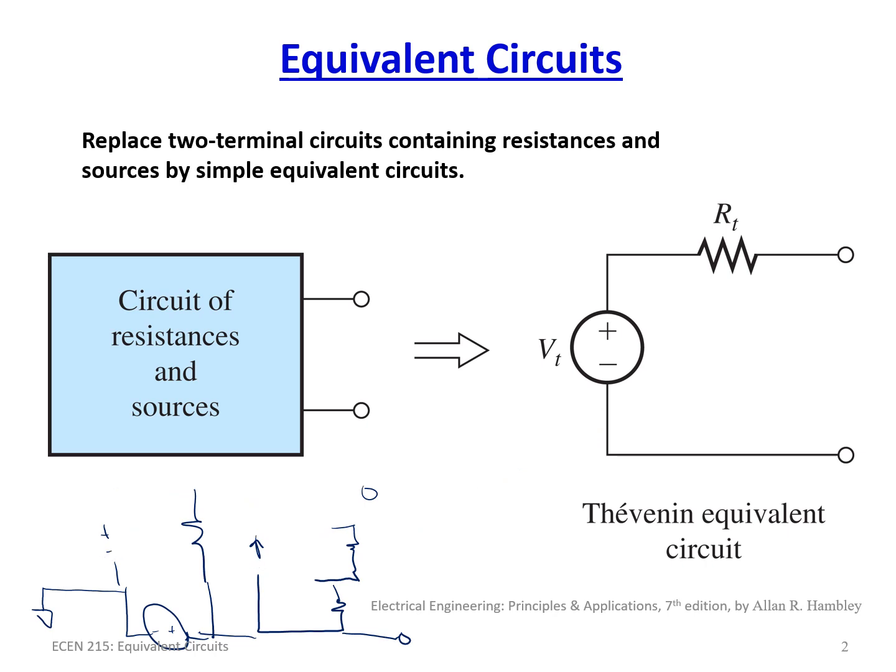Why you would want to do this is you could actually have multiple stages of a design. For instance, say you have an instrumentation system with a set of different pressure sensors or temperature sensors, and you're going to have a stage one where the sensor connects and gets amplified, and then another filter stage where you clean up the signal, filter noise out of the signal, and so on. So usually when you design a circuit system dealing with instrumentation, you have multiple stages.